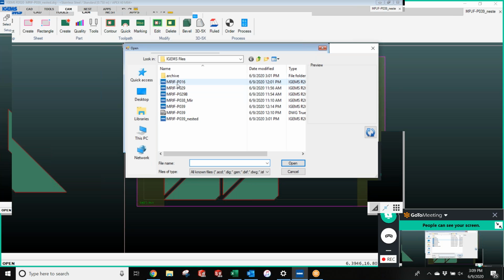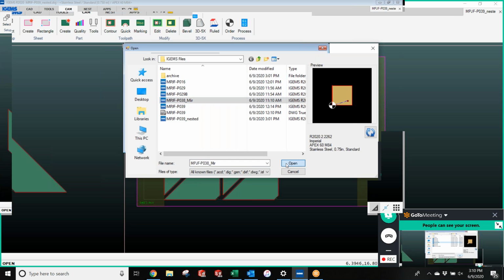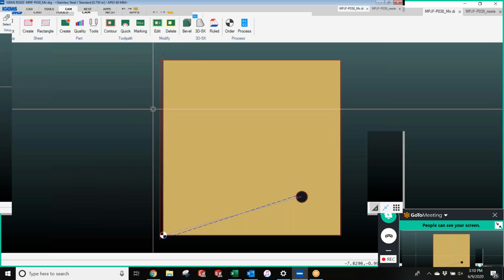It may not be a great example. It's just probably going to be a bigger part than what we would actually encounter. This is probably an 8-inch part with a bevel on it, so it likely will not be tabbed. But the only thing I could see where I would tab a part like this, and I did see this in one, is the piece of 3/4 stainless plate that I have on the table has some pre-stress in it.